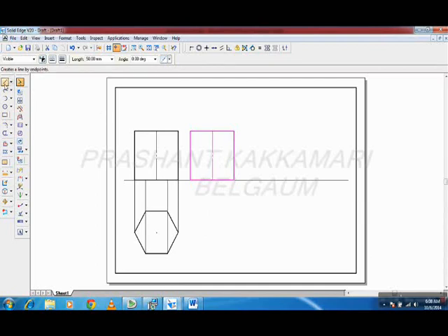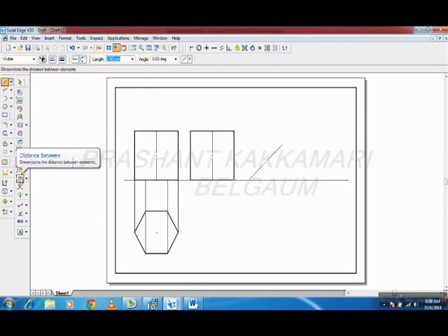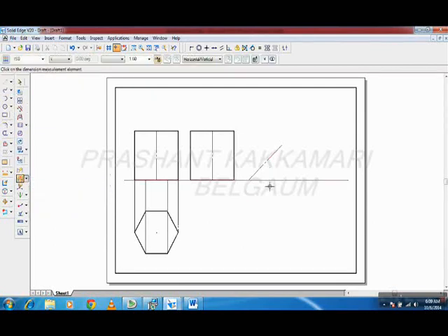So what I can do now? So just draw like this. One line you draw on this base. So this axis is inclined at what angle? It is at 40 degrees. So this is at 40 degrees. Enter. Now this base line or face is perpendicular to this axis. So draw one line there, anywhere on this line you draw one perpendicular line, or touch this line. Now start the line. So it is showing now perpendicular line from that axis. Also extend it.